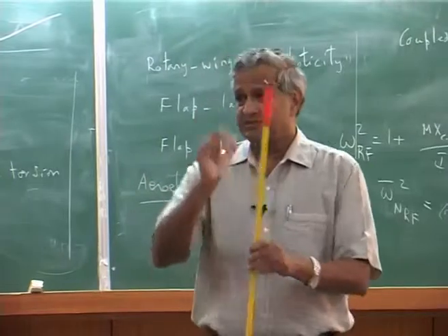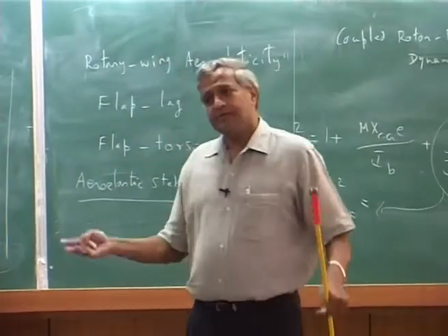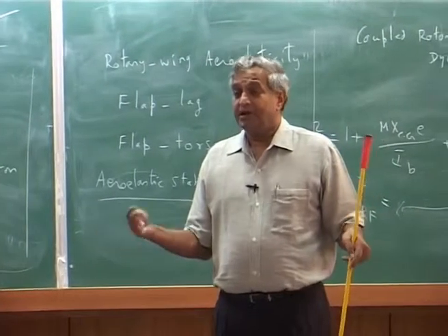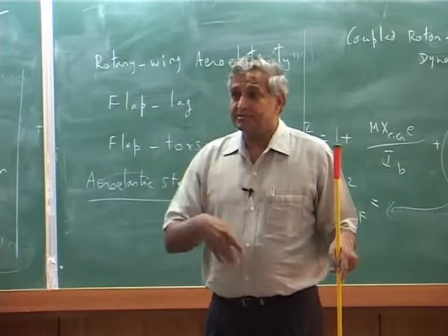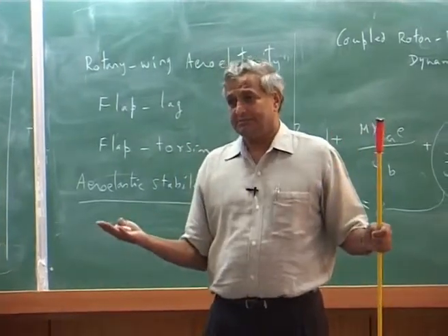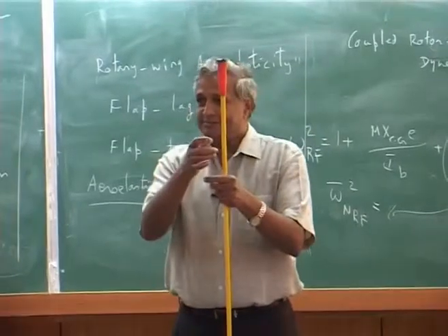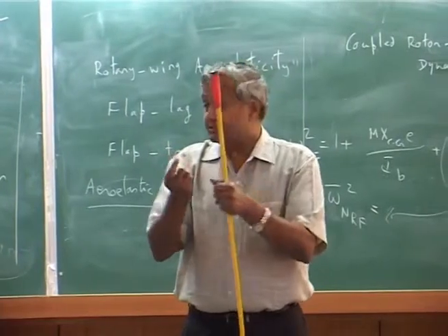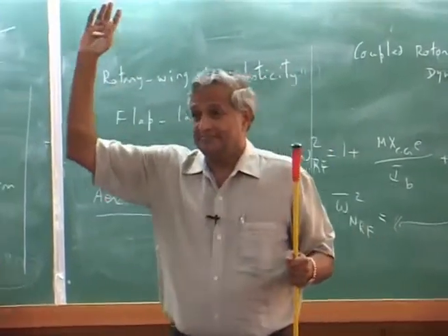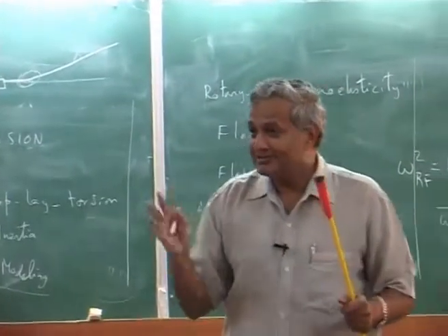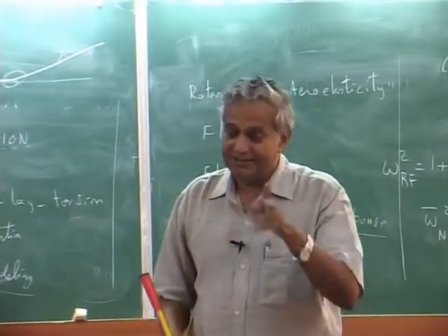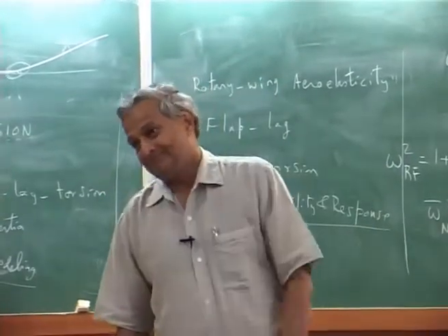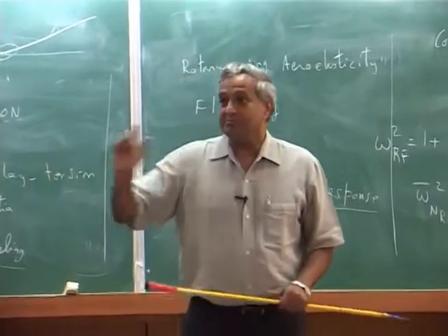See, if you take flap shear load, if it is a 4,000 kg helicopter, it is 40,000 Newton for 4 blades. That means per blade it is 10,000, to support the weight of the helicopter by 4 blades. Shear load 10,000, but centrifugal load is around 100,000. But that does not mean flap load is useless, because that will give you the fatigue, because it will oscillate, all the vibratory load comes here, because it is a bending problem.